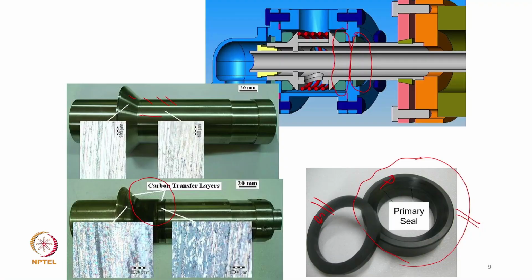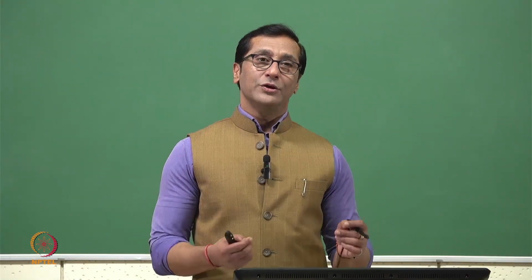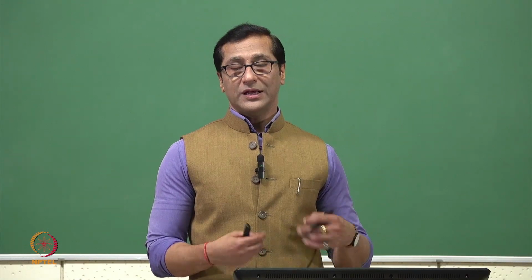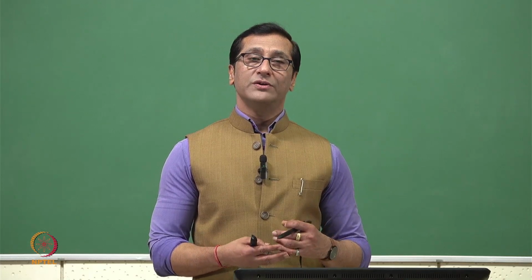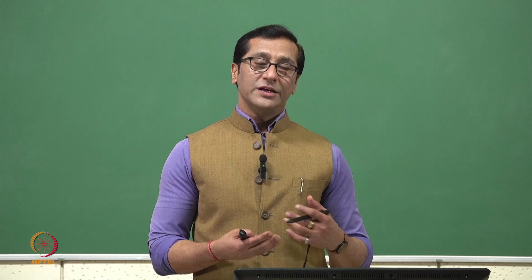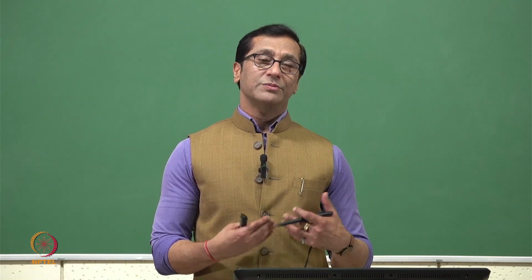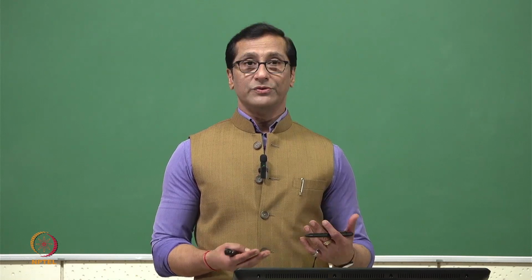You can see without any layer, and now here there is a carbon graphite layer, and this bridges the gap. This transfer of the carbon graphite layer bridges the gap, and then steam is unable to pass out. And here the steam environment acts as a lubricant along with the carbon graphite. In other words, carbon graphite works much better in the presence of moisture, or water vapor.